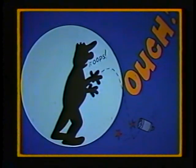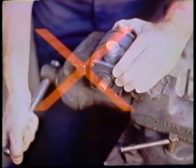During installation, special care must be taken when handling the pump itself. If dropped, its carbon rotor and vanes could crack, causing the pump to seize. Caution: never return a pump to service if it has been dropped. When installing the pump, do not clamp it in a vise with the jaw across the pump body, as it could cause the carbon rotors and vanes to crack.